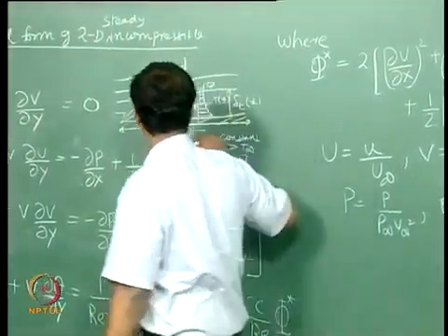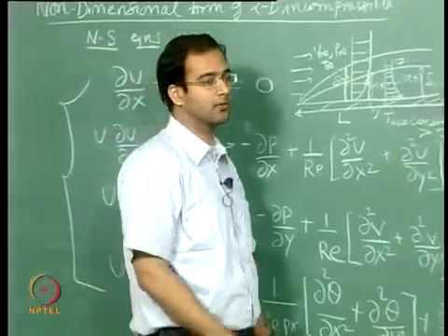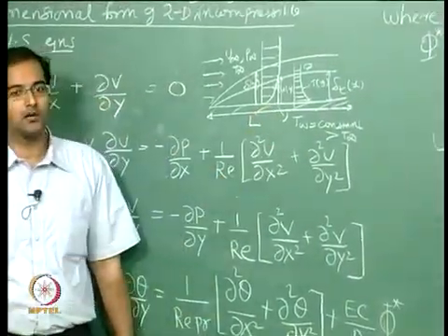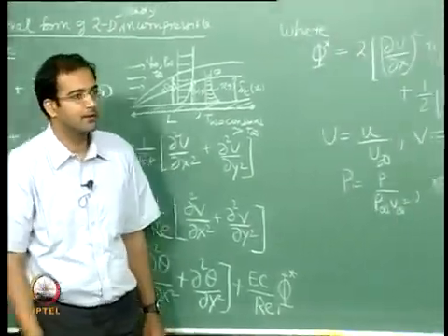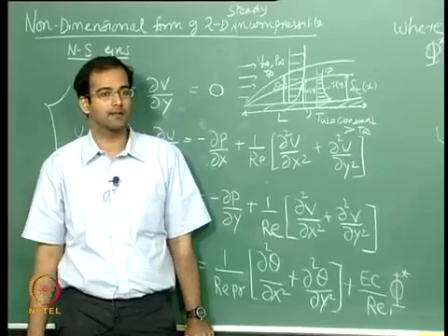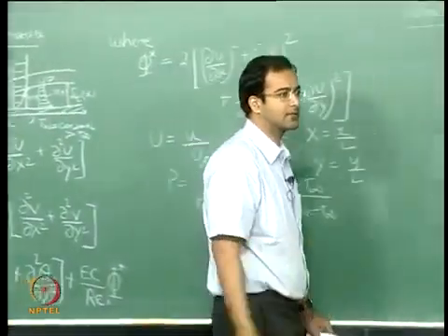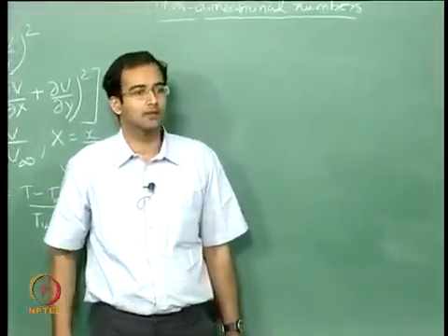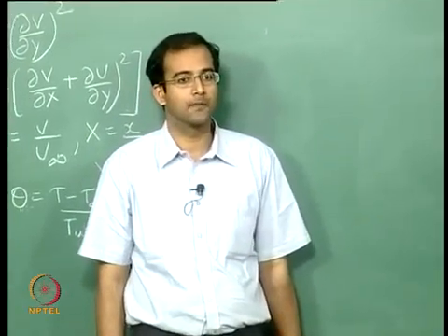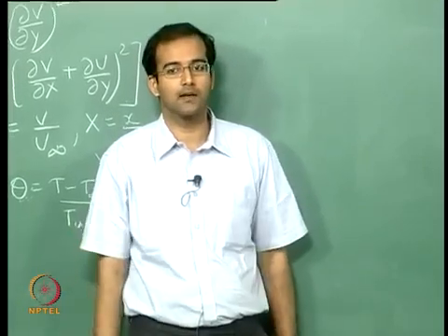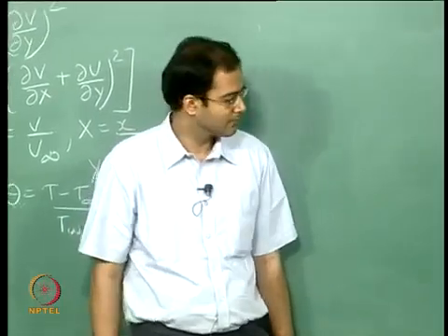It tells you, for a fluid element at a vertical distance H from the flat plate, what the contribution of both advection and conduction is over conduction. If that value is equal to 1, all of this is happening only by conduction. And if it is greater than 1, you know that advection is helping in the transport of heat. So when you are looking at convection, you are looking at Nusselt numbers greater than 1, where the higher the value of the Nusselt number, the better is the heat transfer rate augmentation due to convection.